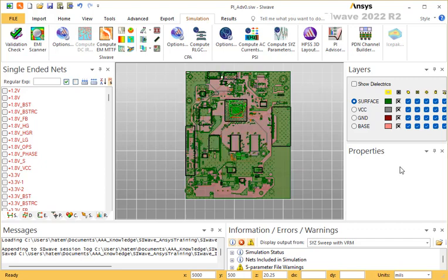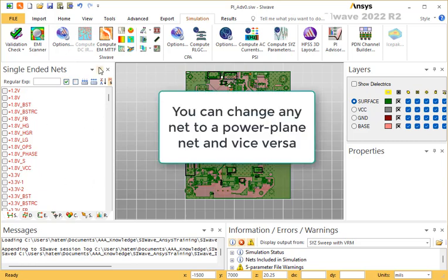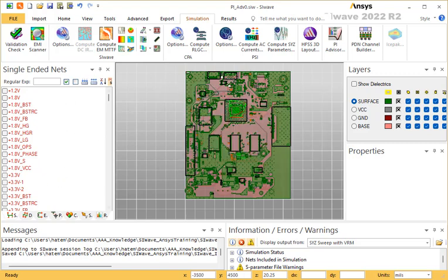We have here a PCB board. It has many power planes, as you can see here. We can select them all and solve them all together. Nothing prevents us from doing that, but we will focus on only one of them. Notice that SIwave put all power planes in red, because it treats them in a different way when it solves for power integrity.